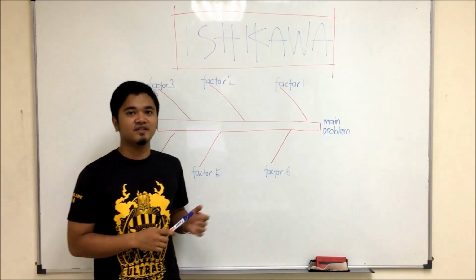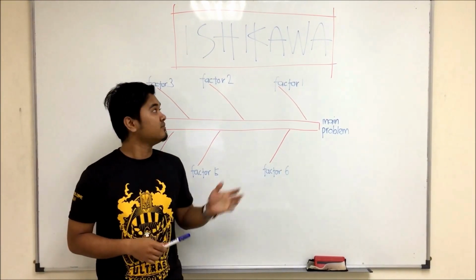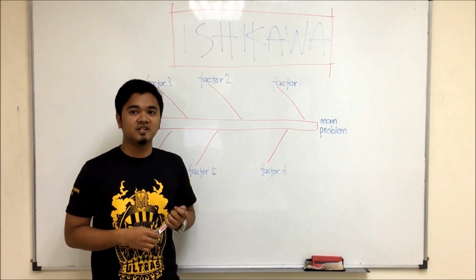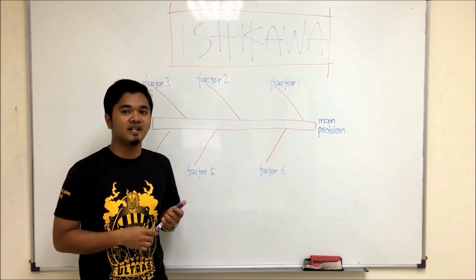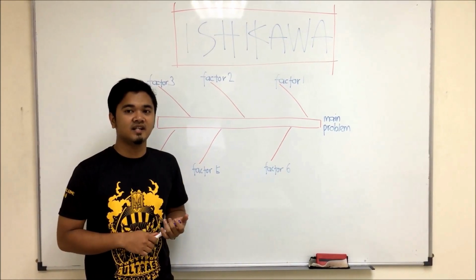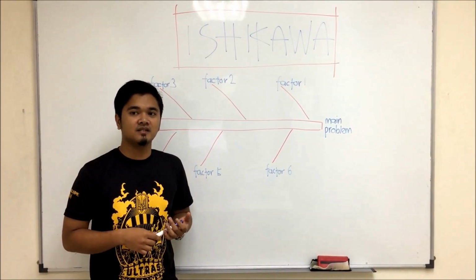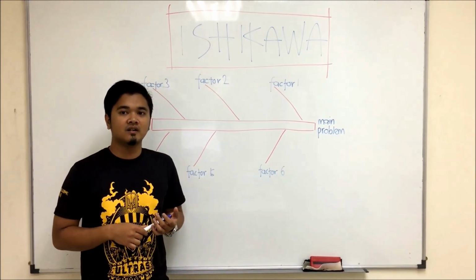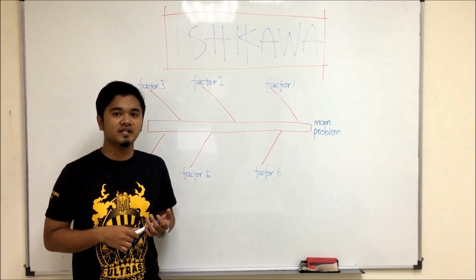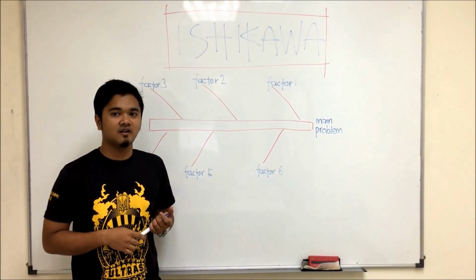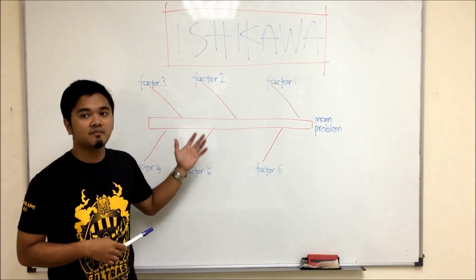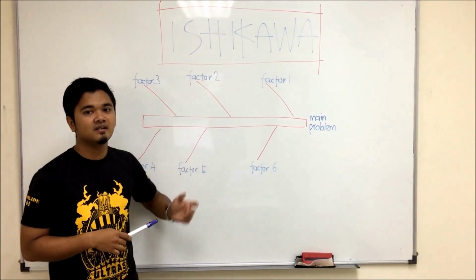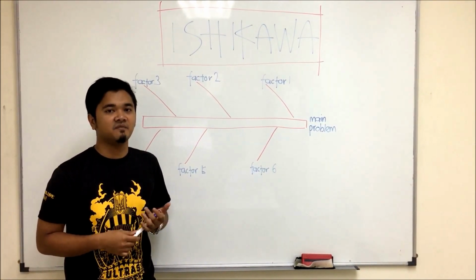This is the first method to investigate the causes of failure. Common uses of the Ishikawa diagram are product design and quality defect prevention, to identify potential factors causing an overall effect. Each cause or reason for imperfection is a source of variation. Causes are usually grouped into major categories to identify these sources of variation. The categories typically include people, machine, material, measurement, and environment.